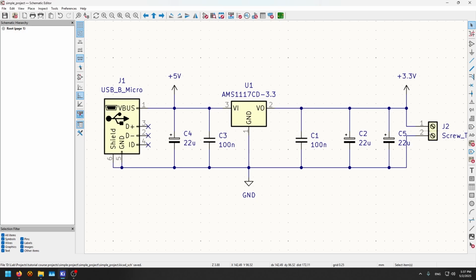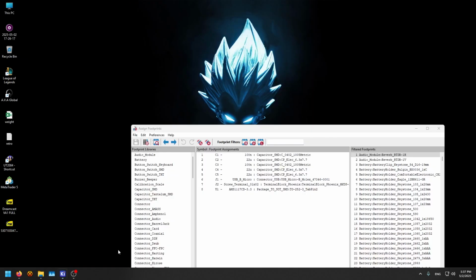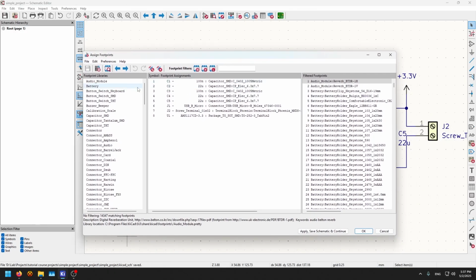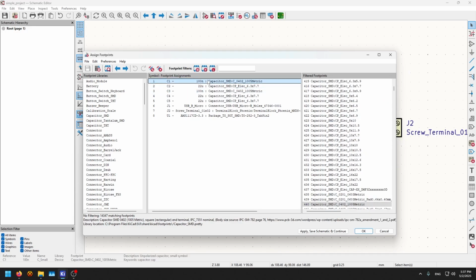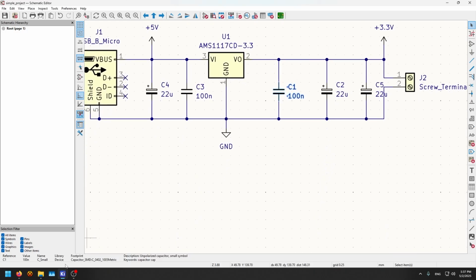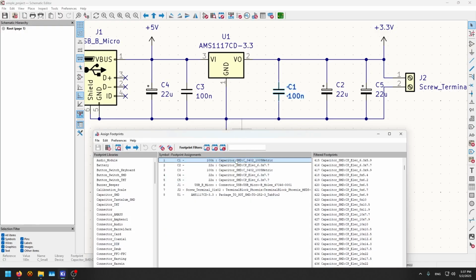It's a generic connection. Okay, so it doesn't have a footprint. How can we assign the footprints? We can use them from here. So you're gonna go through one by one. For example, this capacitor. It highlights the capacitor right here. Let's go back. It highlights C1.